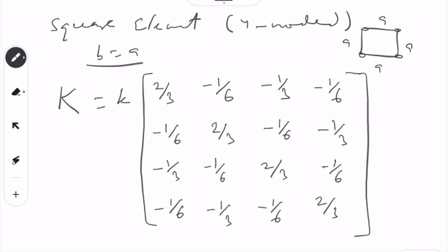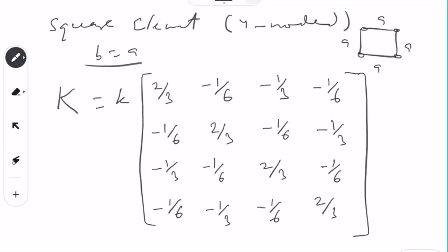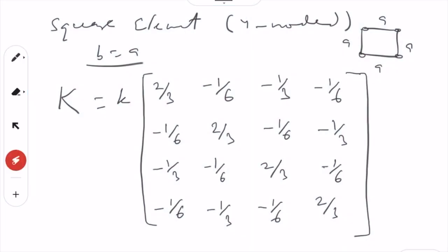Okay, so done. So this is how the four square matrix looks. Next, we can simplify this further. We can take this 6 out, so we will have k over 6 here, and then we write all the values: 4, minus 1, minus 2, minus 1, and so on. We can also write the simplified one, so that big K is equal to a small k over 6, multiplied by 2, so it becomes 4 minus 1 minus 2 minus 1.